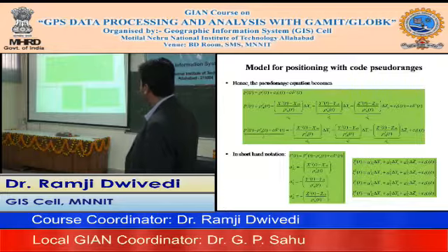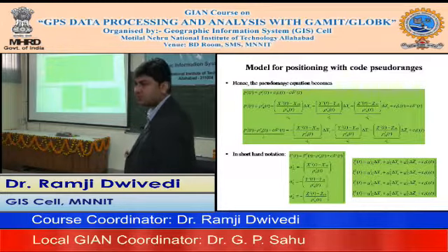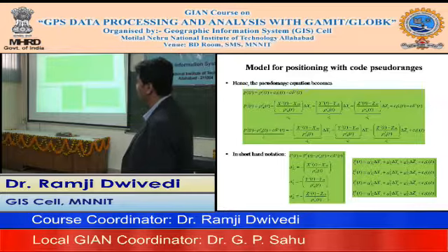Then the receiver clock offset and the satellite clock offset. This term we eventually know from the navigation message. With the help of the navigation message, this becomes your prime observable, isn't it? So this is nothing but the pseudo range, the initial approximation with respect to the initial coordinate, and then c times the clock offset from the GPS time.